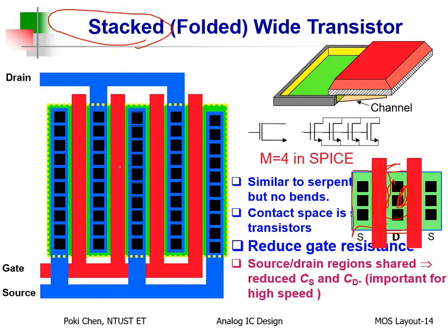All right, so we reduce. Okay, how much can you reduce? Briefly speaking, 50%. Okay? Why? You can see. Oh, I told you already. Where will be the parasitic capacitance? 3 sidewalls and the bottom plate. Right? By overlapping, we share the same bottom plate for both transistors.